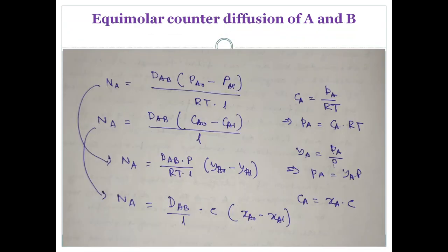And for equimolar counter diffusion, we have seen this is for gas phase, when partial pressure is the driving force, and in terms of concentration, that is applicable for both gas phase and liquid phase, and this will be applicable for gas phase, for mole fraction as the driving force, and this is the expression.